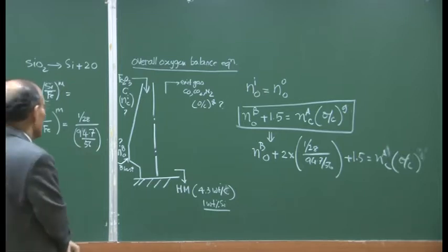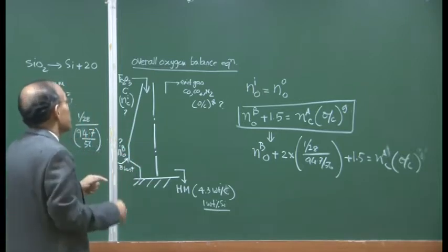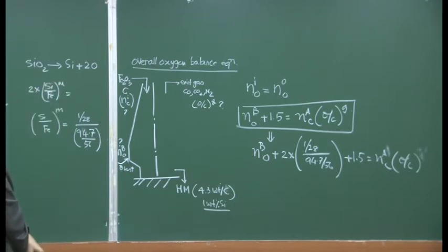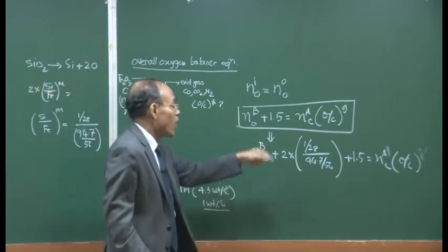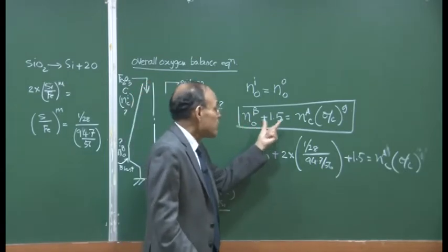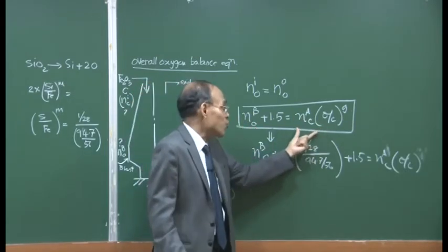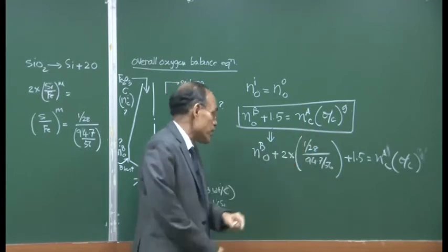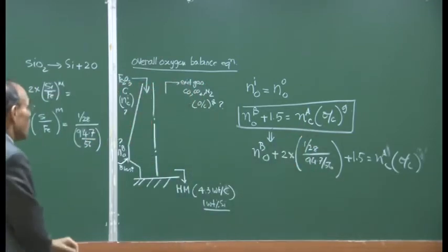So some modification will be necessary. All those parameters which contribute to oxygen input into the system can be taken into account, and that input is going to be reflected in the output both in terms of the coke rate as well as O by C gas composition.